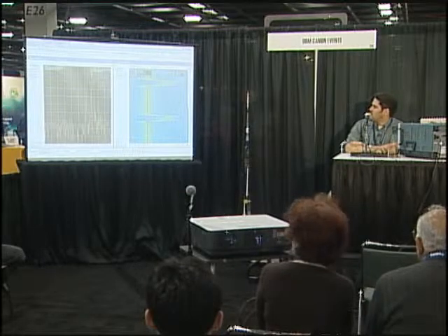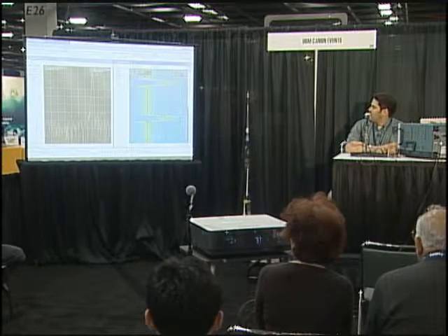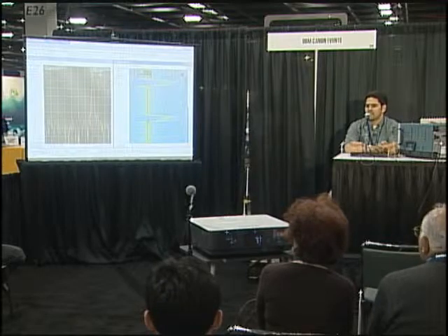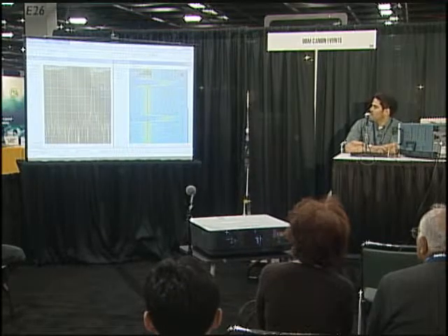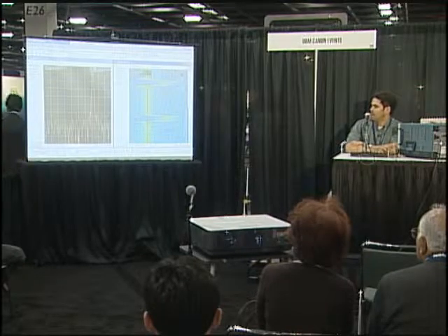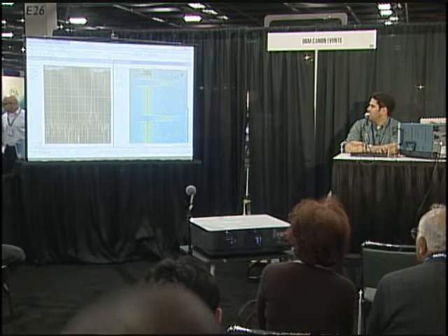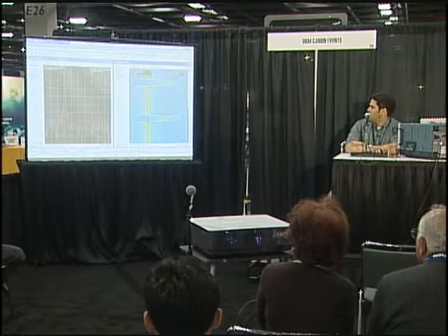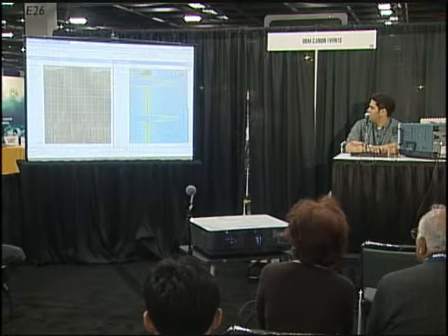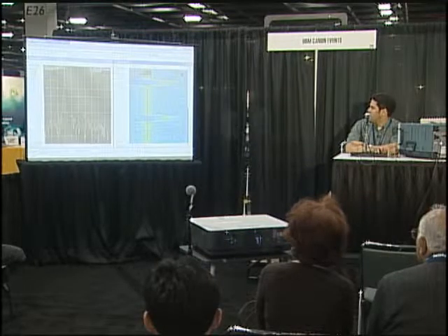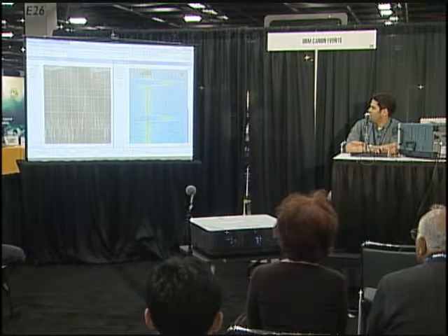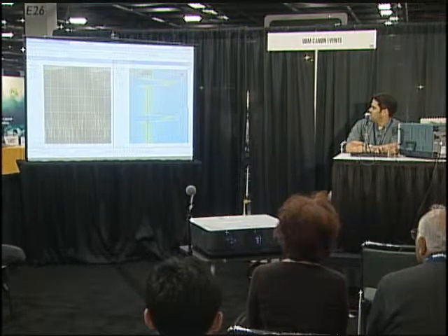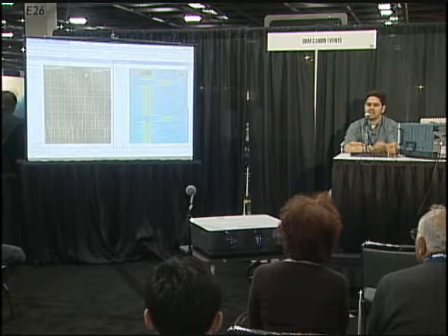There is another mask that will also work. Because the DPX display told us that the signal was going to come over here, then I could do this mask, right? This little dip here. Because I know that the signal is going to go over there, right? So if we see how this trigger happened, again, the T is the trigger point. You can see how the signal swings to the right and somewhere around here hit the mask. There you go. So once again, this acquisition happened because the signal hit the mask.